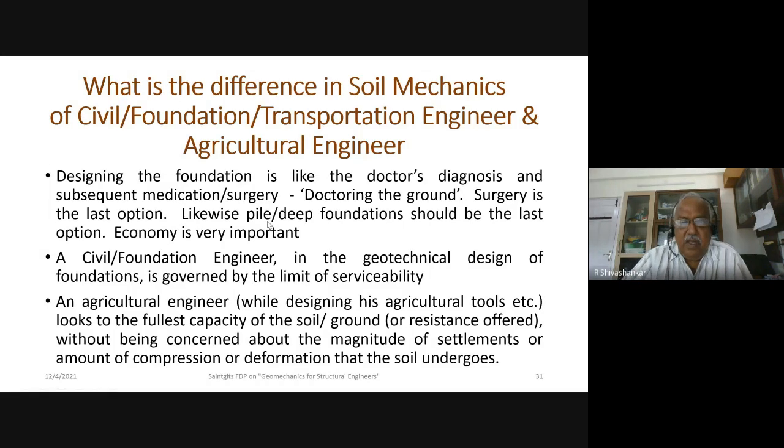Now, in the design, the geotechnical design is governed by limit state of serviceability. That means we are restricting the settlements because there could be so many service lines below the building. There could be sewer pipes, there could be water supply pipe, gas pipe, and so many cables. And we don't want all of them to get damaged. So our building codes restrict the settlements.